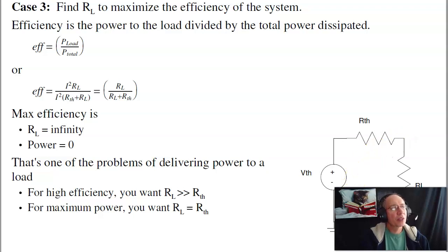That's kind of where Thevenin equivalents are useful. With a Thevenin equivalent, I can see how the load resistance affects the efficiency and the power, whereas a more complicated circuit would make it much harder to see. And with that, I can see the basic rules. If I can vary the load, R load matches R Thevenin. If I want to vary R Thevenin, make R Thevenin 0. That's lecture number 11, Thevenin equivalence and max power transfer.